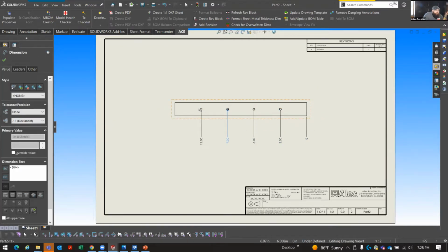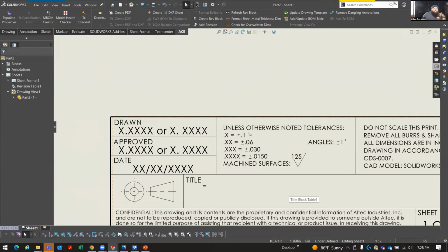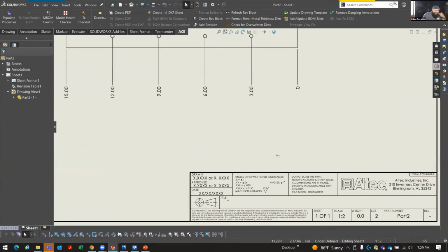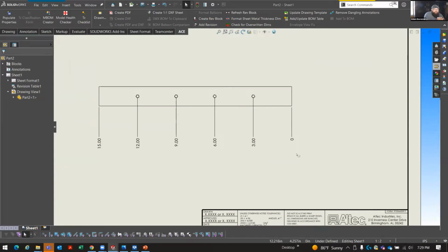So this is all really good examples of design intent, right? Now, because we have this set up this way, if you look at our giant tolerances compared to some people, I mean, look, we have 16th of an inch tolerance on 2 decimal places. It's because we make things that are 30 feet long. And if I can look at it and go, that's enough. Can we use a hammer to put it back in place? Yes, then we're good. But because this is the way you set it up, you've got the design intent to where you've only got a plus or minus 16 of an inch on each hole. Now, if we were to daisy chain them, we know that they could stack. You have this big giant tolerance stack up.